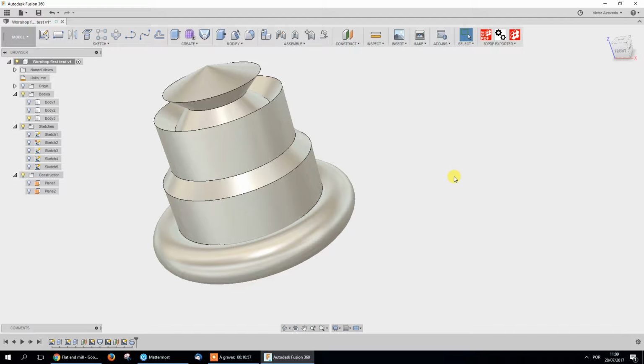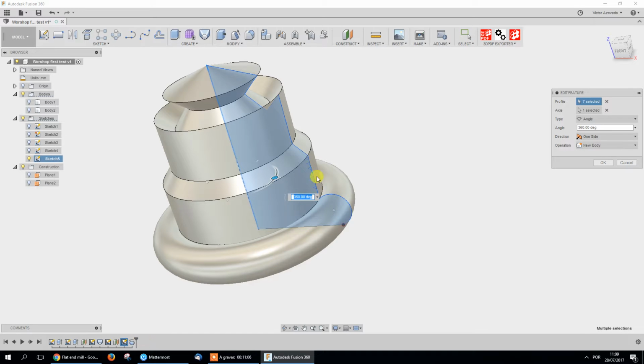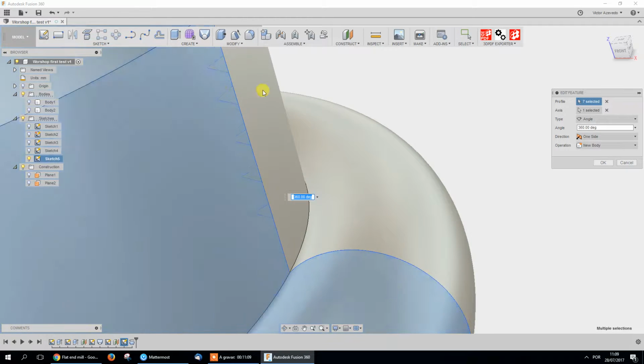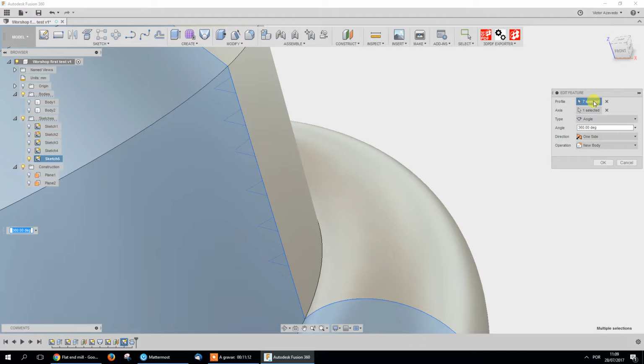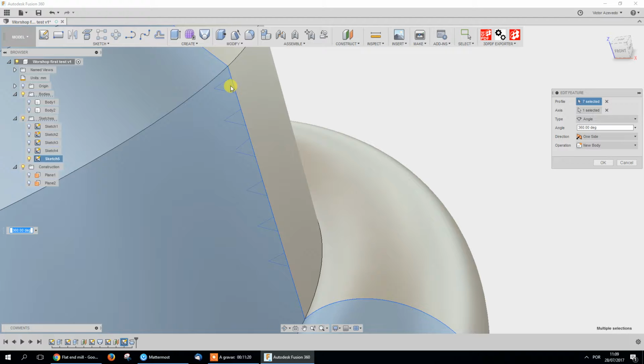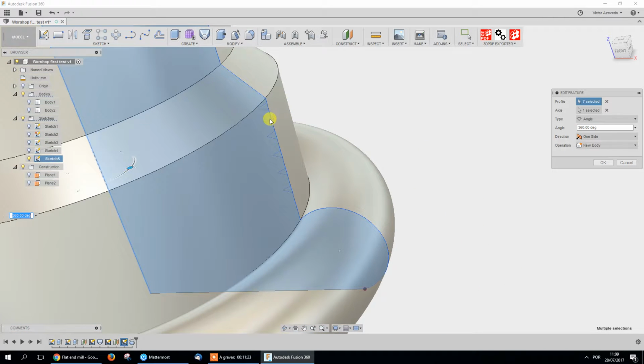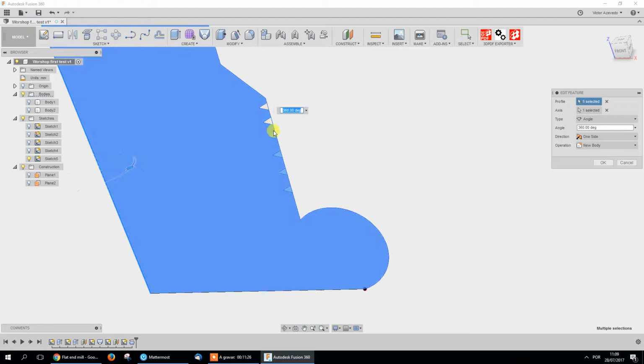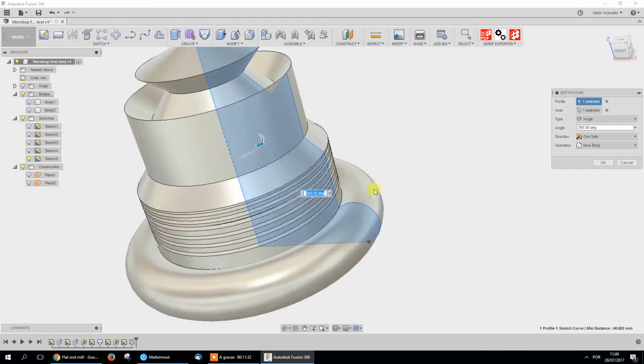You closed the sketch and didn't change anything, right? So that's why, well, that happened because when you had something, it adds to the profile feature. So you need to hold control and deselect what you want, or at least the first one. It's not working. Okay. Hold control and deselect what you don't want, and it will. Hold control. Control.